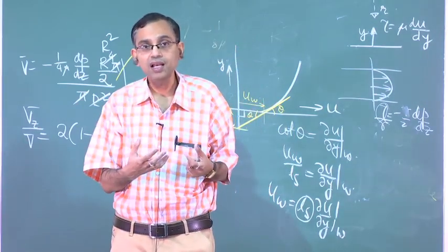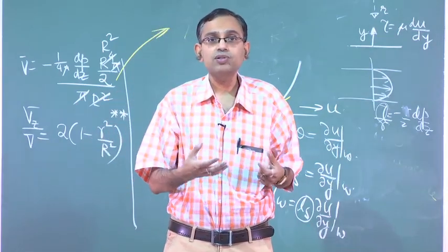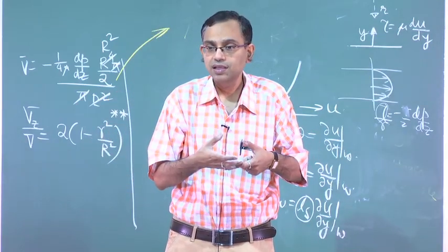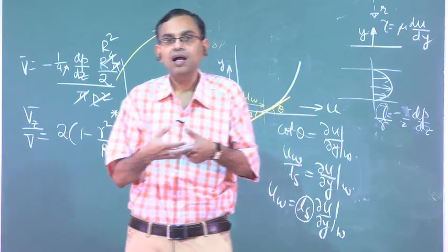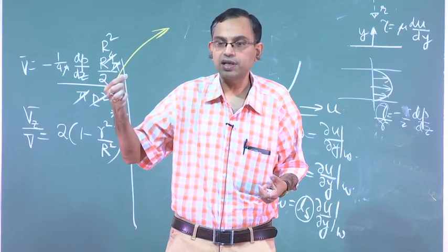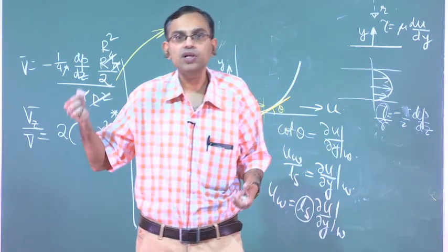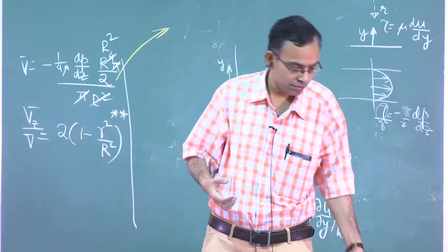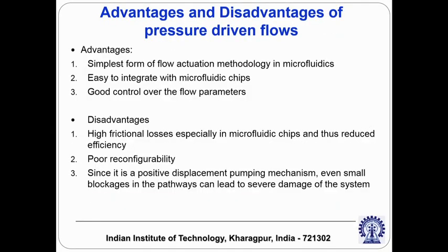In the microscale it could be that you can use roughness as a blessing in disguise. The roughness of the wall might trigger the formation of small gas pockets, and liquid can flow on top of that without creating much of a frictional hindrance.